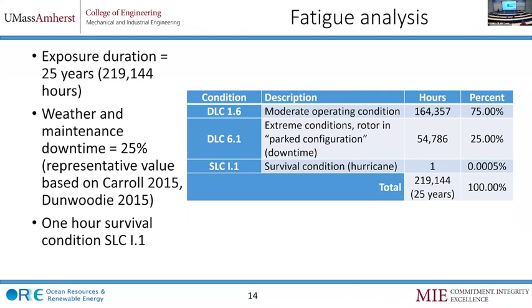so it's not producing power. And for fun's sake, we also threw in one of the survival conditions. Based on that, we looked at the number of hours, and then depending on the number of wave cycles, you can count how many times and what sort of load ranges the mooring line is subject to cyclical loads, and from there you can calculate a level of damage. The more proper way is to use a scatter diagram, where different environmental conditions have different levels of probability, and that needs to be brought in when you do a proper fatigue analysis. But this one sufficed for the purpose of this project.